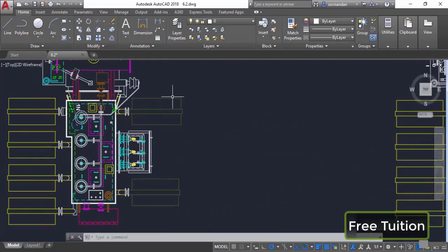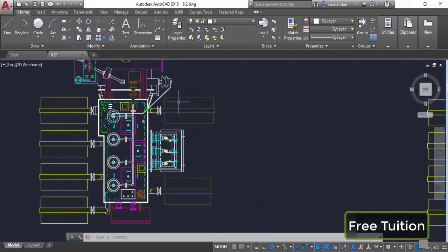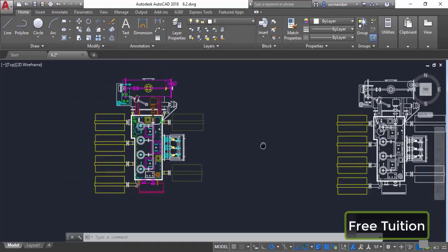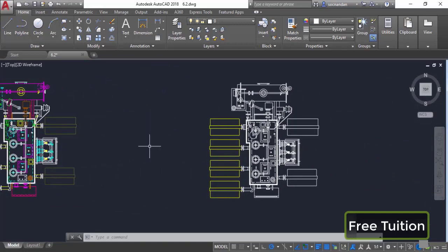Here we have transparency applied to this part of the geometry. Now if you compare it with this part of the geometry, you'll notice that this one is quite bright with 0% transparency, and here a transparency of nearly 70% has been applied. So that's why the object looks a little bit dimmer than these objects. Now in order to apply the transparency, again you need to go to the properties. So in this case, I'll first select the objects.